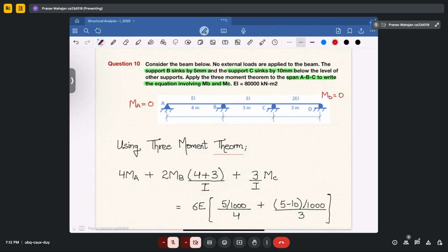Then we have found out the flexibility coefficient. How did we get the flexibility coefficient? We have applied a unit load at the redundant force, and whatever displacement you observe at the corresponding point becomes your flexibility coefficient. Then using the compatibility equation, we have determined the unknown force.